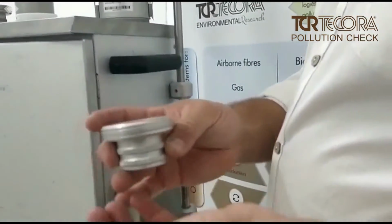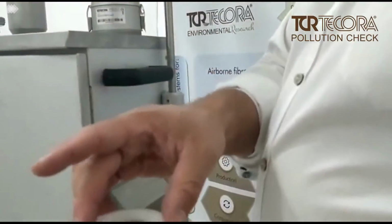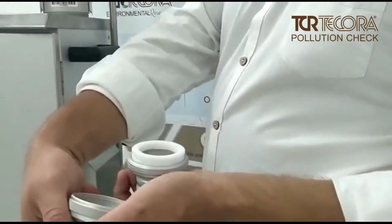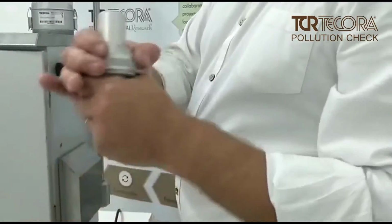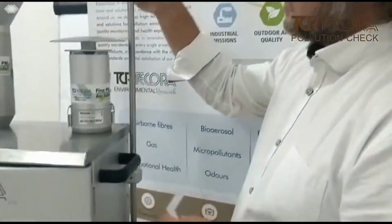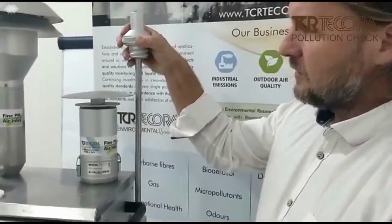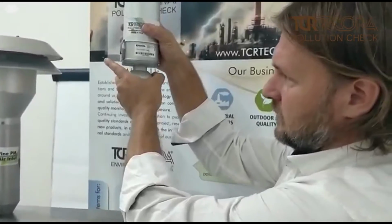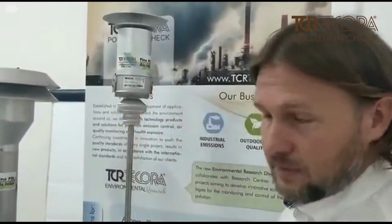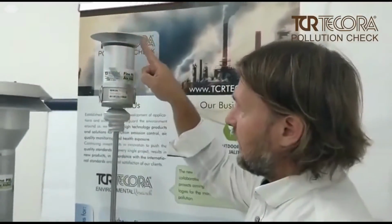This is the filter holder for the filter cartridge, where you can set the membrane inside. Then you can just put it here and close it. Then you can enter here and install the sampling head. Perfect. So this is the way we enter.